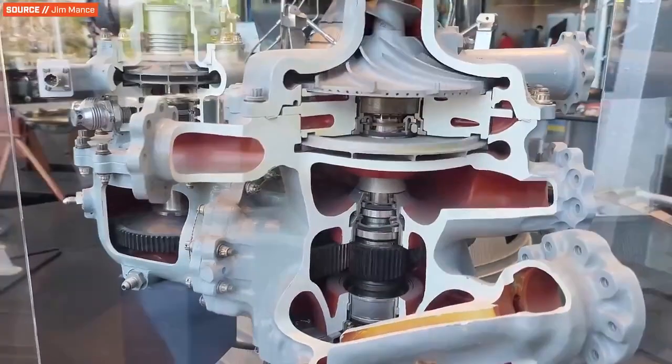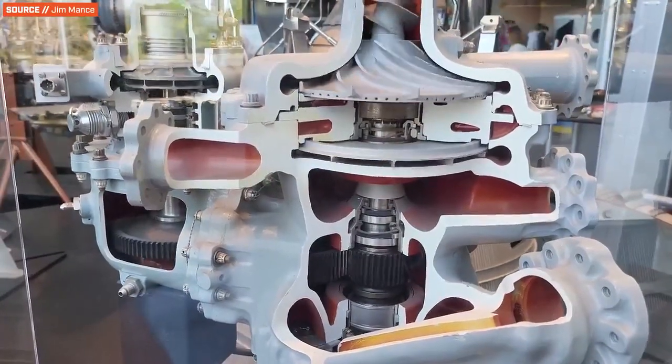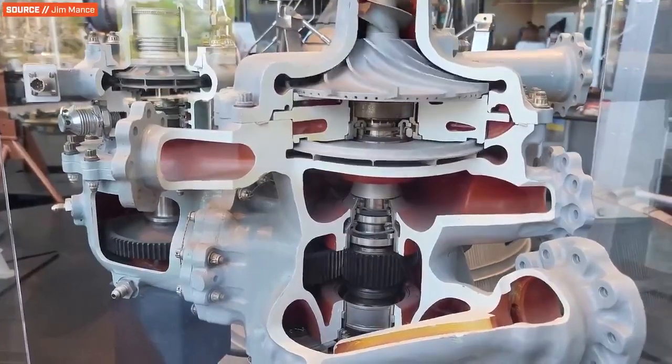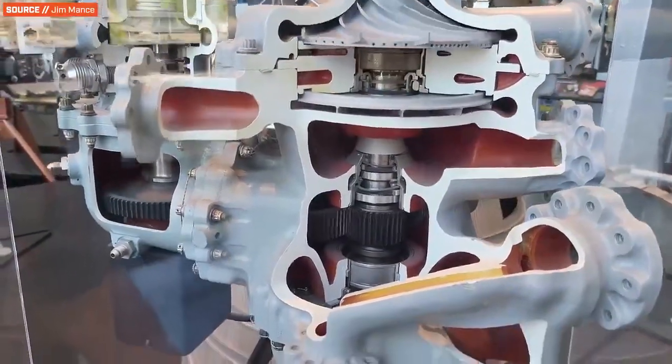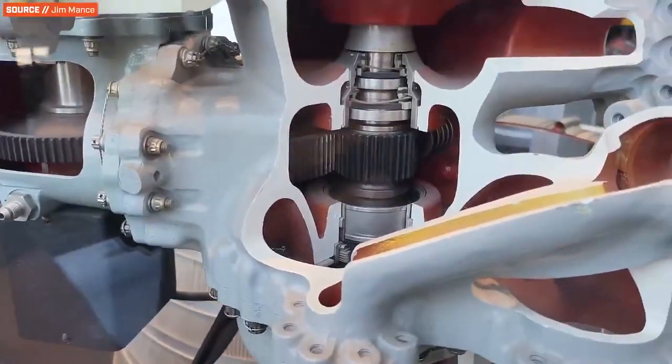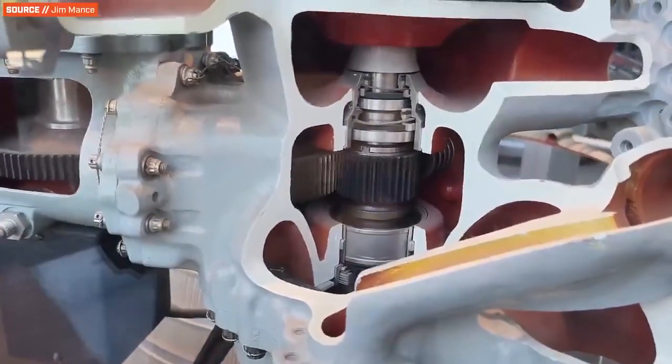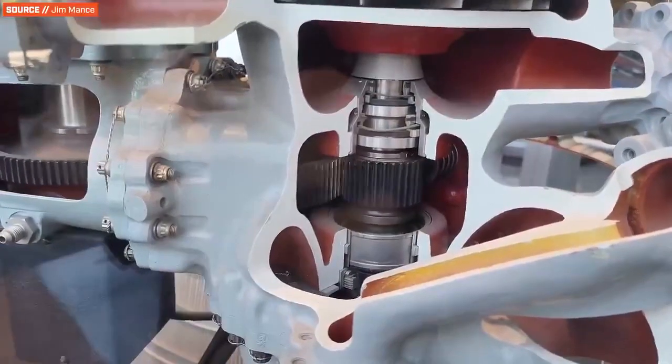In the case of a hydrogen-fueled engine with a single turbine, engineers might even need to employ a gearbox inside the turbo pump so they can direct the required amount of speed and energy to the fuel pumps and send less to the oxygen pump, which doesn't require nearly as much energy. So now you've again traded one form of simplicity and efficiency for another complication and more moving parts. But it is very efficient, and it's an effective way to use what is basically free energy in the system, heat, to power your pumps.